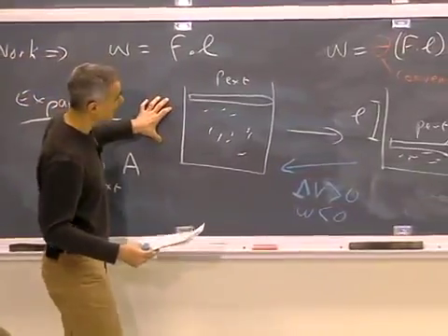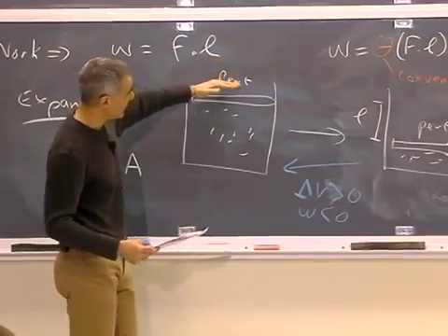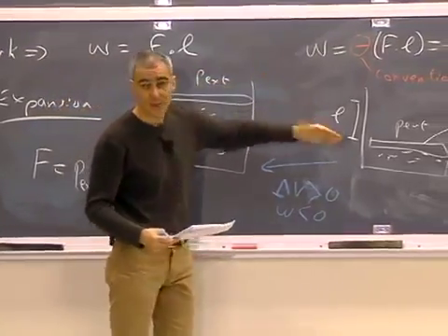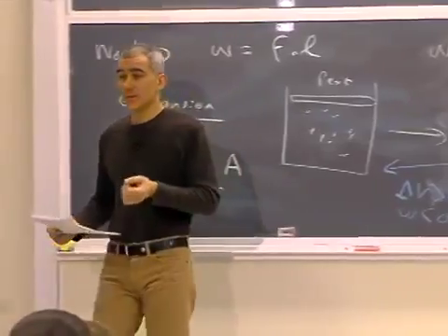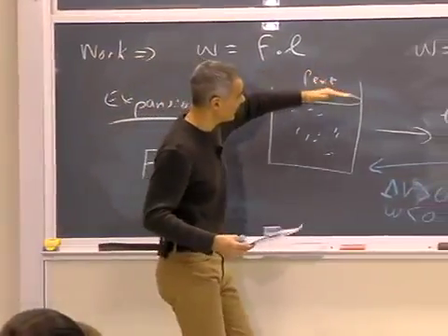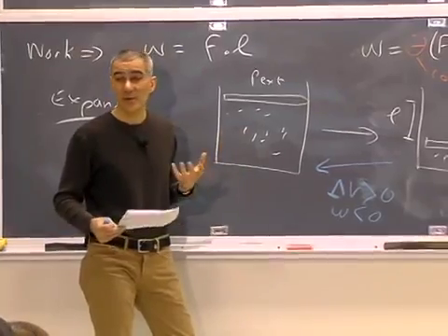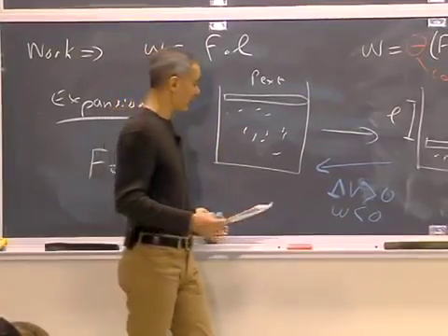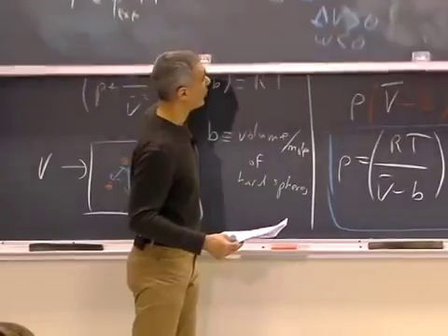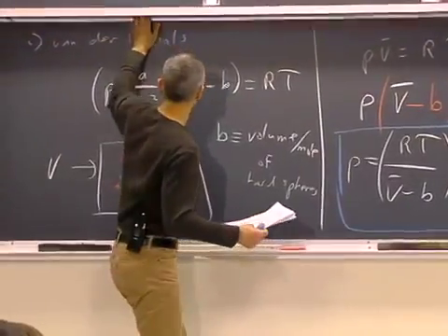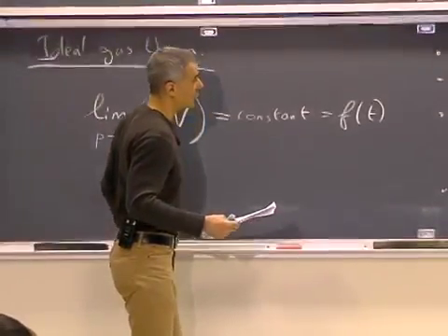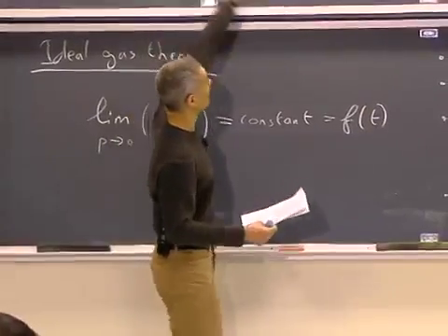All right, this is an example where the external pressure here is kept fixed as the volume changes. But it doesn't have to be kept fixed. I could change my external pressure through the whole process. And that's the path. We talked about the path last time being very important, defining the path. So if I have a path where my pressure is changing, then I can't go directly from this large volume to this small volume.